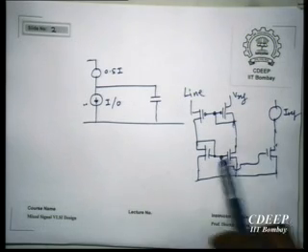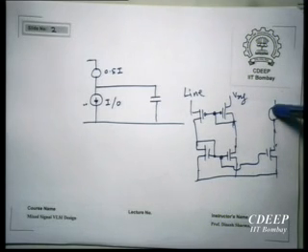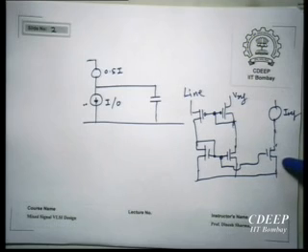To give you an example, suppose 15 microamps of I0 was coming here. Suppose I have a 10 to 1 ratio. That means I have 150 microamps of I0. Then I can have a 75 microamp source here. Right? So when this is 0, I have 75 microamps charging the output capacitance, and when I have 1, that is 150 microamps, there is a net 75 microamps discharging the output. Okay?